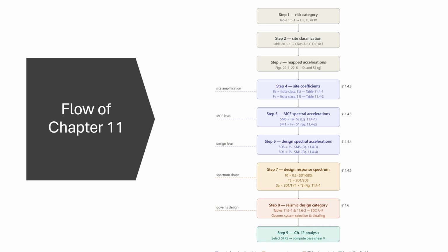So then you take that, and then you get your response spectrum. This is based on your period and the different frequencies at which your structure is going to oscillate or vibrate, which depends on the period response of that structure. So a stiff structure such as a steel moment or a concrete frame is not very ductile.